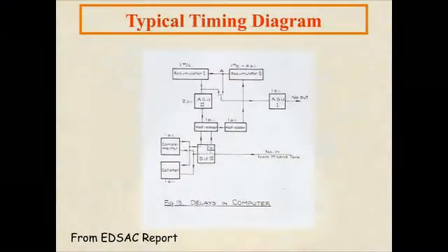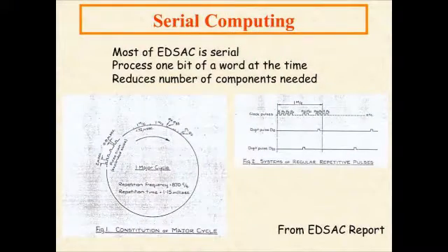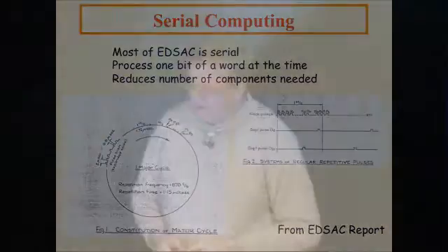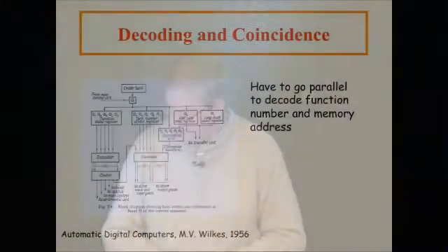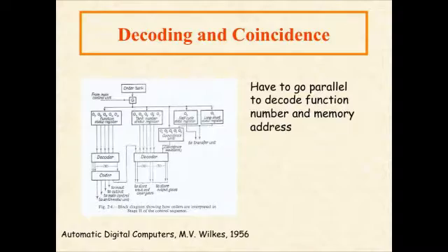And other diagrams tell you what the timing is. PI on those diagrams is pulse intervals, and that tells you what delay is permitted between the signal leaving one part of the machine and getting to another. So some of those diagrams are really quite helpful. From that, and information about the overall timing of the central clock that drives the serial system, we were able to build ourselves a logic simulation.